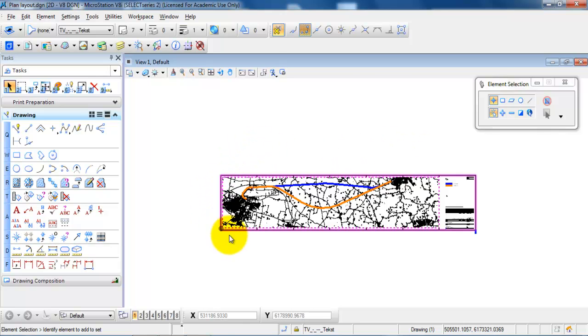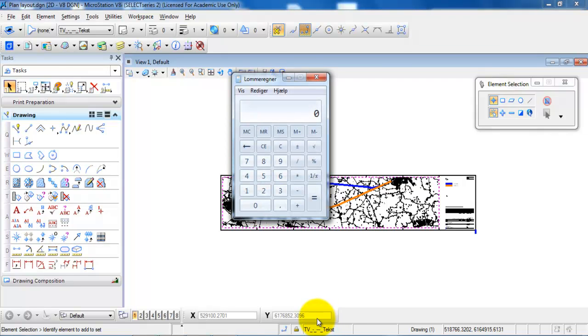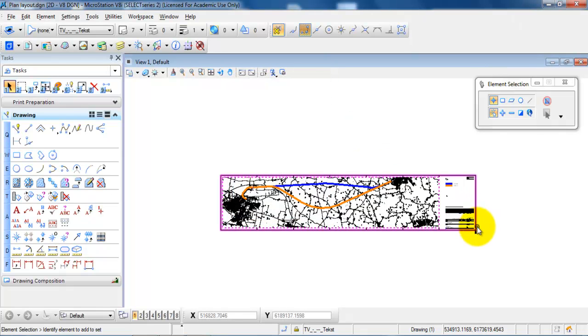So we have a total of 7 sheets in this case, and one sheet corresponds to 210 millimeters times 7. So the overall width of the drawing is 1470 millimeters, and the drawing corresponds to one A4 sheet in the height, which is 297 millimeters.